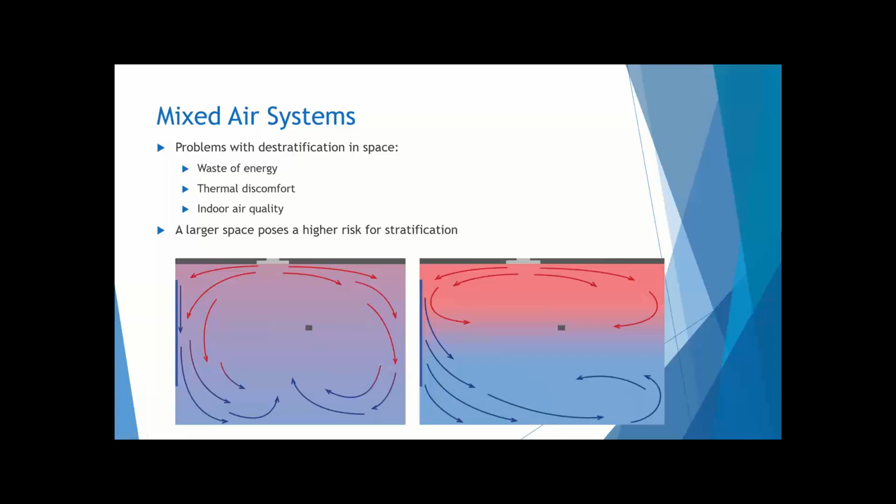Eventually it could result in a waste of energy, thermal discomfort, and poor indoor air quality, because you're not actually bringing that heat down, or you're not mixing that space well in general. This is bad in a small system, but it's pretty easily fixed. But in a high bay system, you could end up with quite a bit of stratification, and you don't want that. So let's keep going.